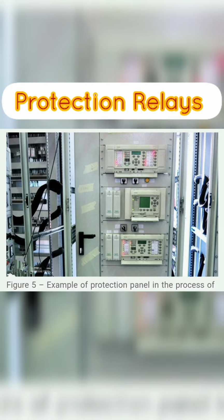Although the principal function of protective relaying is to mitigate the effects of short circuits, other abnormal operating conditions arise that also require the services of protective relaying. This is particularly true of generators and motors. A secondary function of protective relaying is to provide indication of the location and type of failure. Such data not only assist in expediting repair but also, by comparison with human observation and automatic oscillograph records, they provide means for analyzing the effectiveness of the fault prevention and mitigation features including the protective relaying itself.